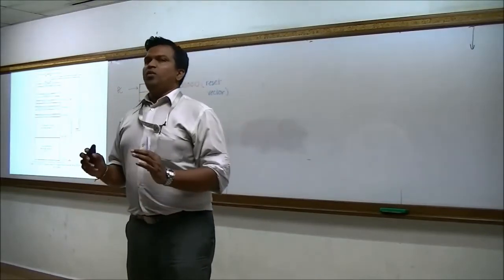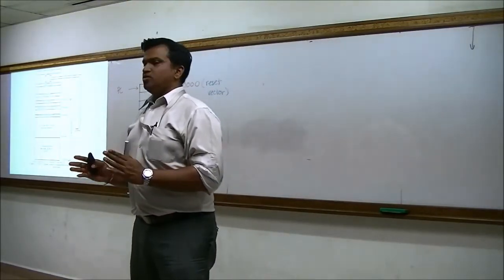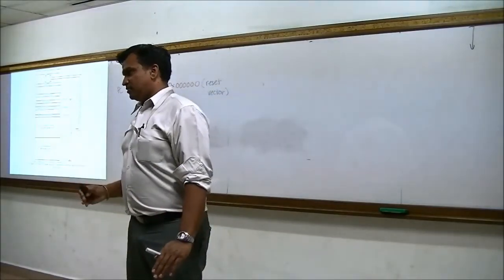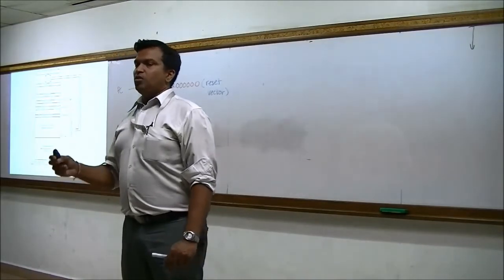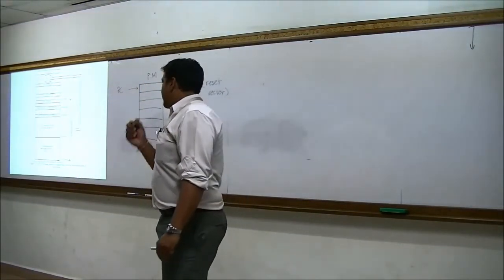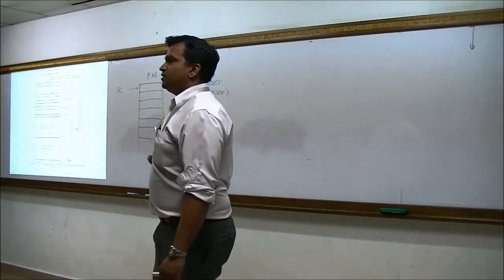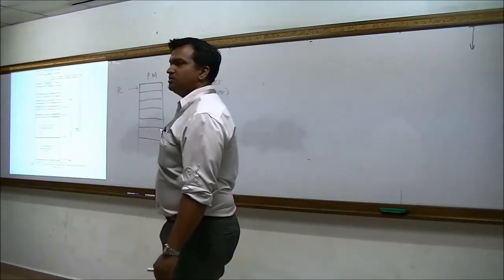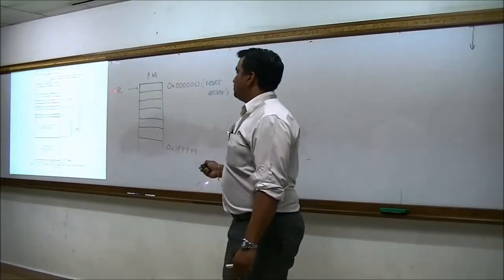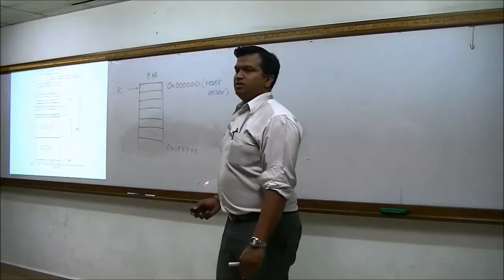For now, you need to understand the capacity of program memory. Based on that capacity, we have already derived the range of the program memory address. You also know that each program memory location can only store 8 bits or 1 byte. And you have learned the term reset vector, which is affiliated with address 0, which means whenever you reset a system, the PC, the program counter, always points back to address 0.